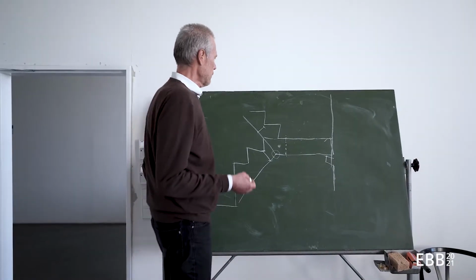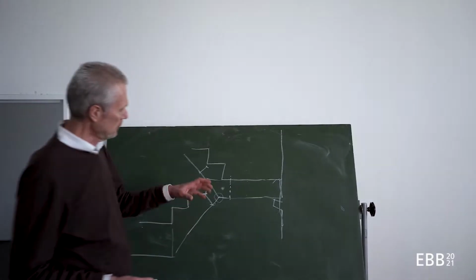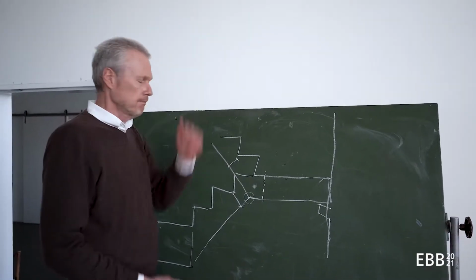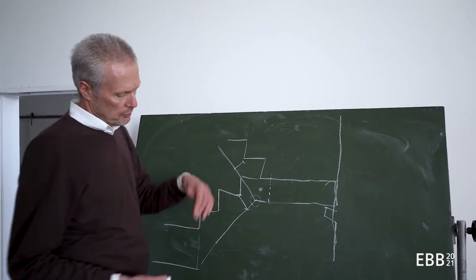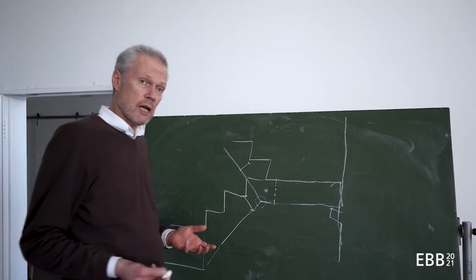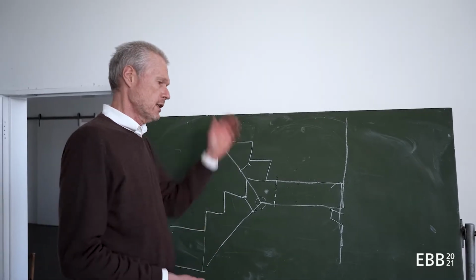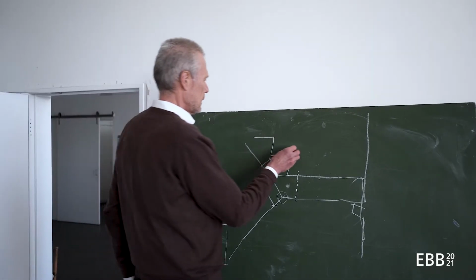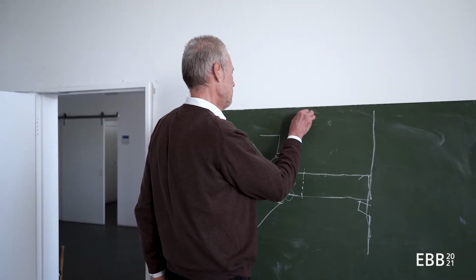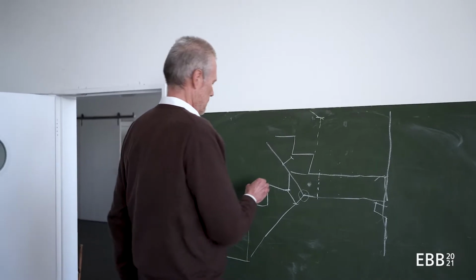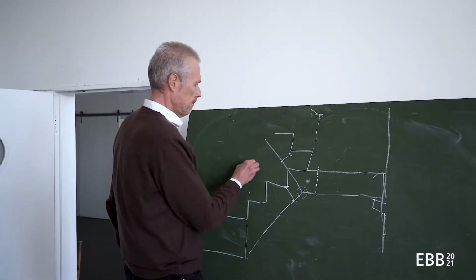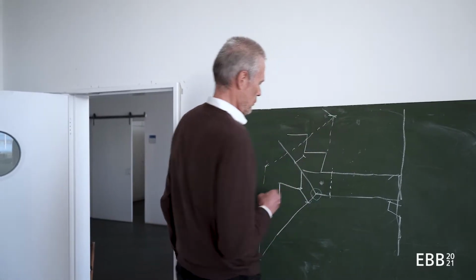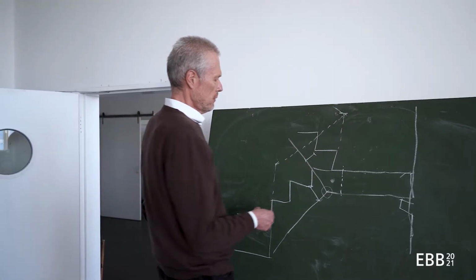So yet another factor is the handrail, because it should be at least 90 centimeters high. When the drop height is larger than 12 meters, it has to be 1 meter 10. But here it could be 90. So if it's 90 here, then it's 90 here as well. And you can see that here both of these should be meeting in one point.